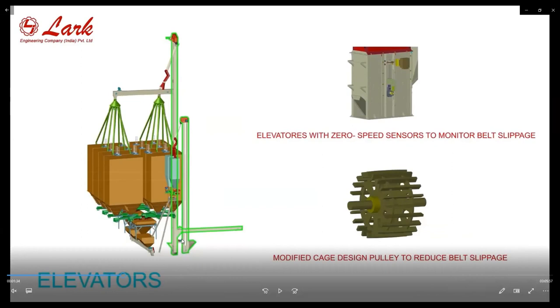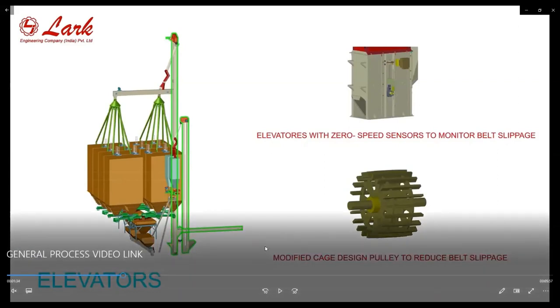Then what will happen? There is heat generation, there is wearing of the rubber of the belt, and there may be failure or breakage of the belt, or even in some cases, if the heat is high enough, there may be a fire in the elevator. To reduce that